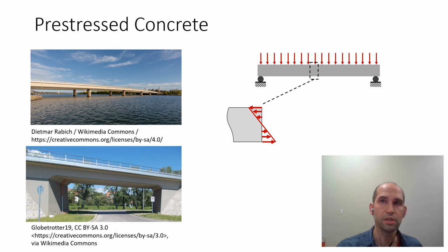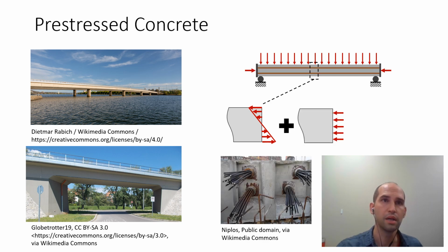So what engineers commonly do is apply a compressive prestress to the concrete sections using steel cables that are under tension. This shifts the stress distribution so that there are larger compressive stresses, which concrete is good at accommodating. This allows the concrete beam to withstand a lot larger forces overall. There are some great videos that expand on the concepts behind prestressed concrete, and I'll include a few of the links below. But in this video, we'll formulate an example question based on undergrad level knowledge of failure theories to think about some of the numbers behind how beneficial this prestress process can be.